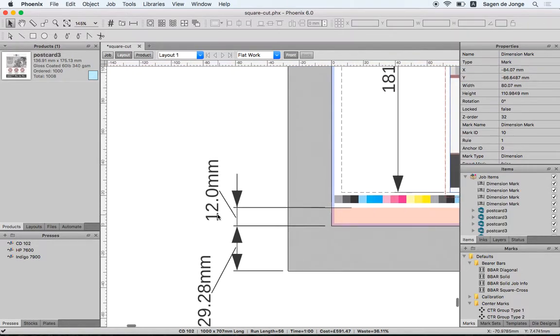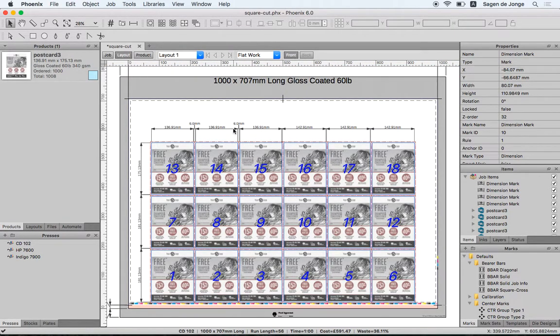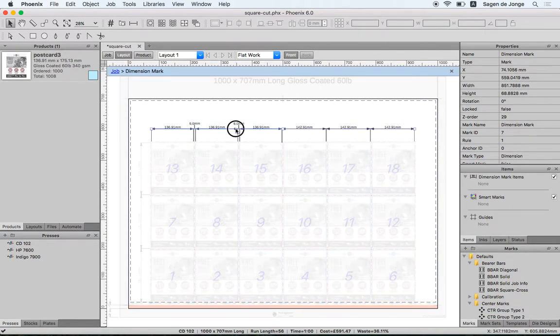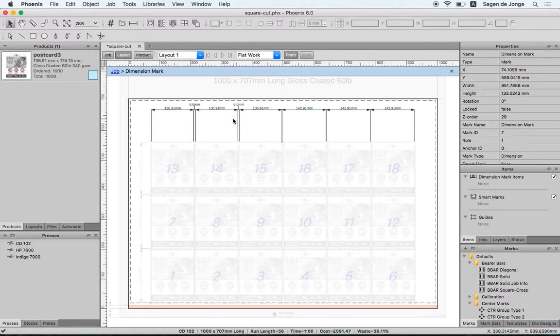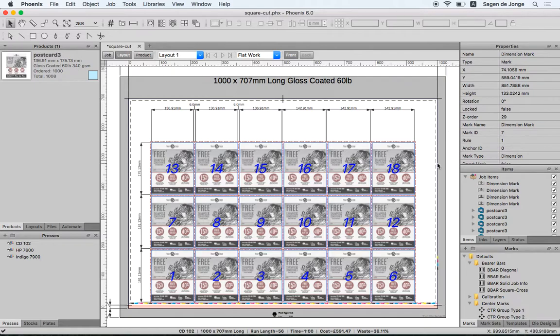And you can go in and edit the positions of marks you've created as well. Say this mark, for example, say I want to move it up a bit higher. I'll double click on this, and now I can click on the bar and move it up a bit here, and now that changes the position of that. So that's doing drawing manual dimension marks.